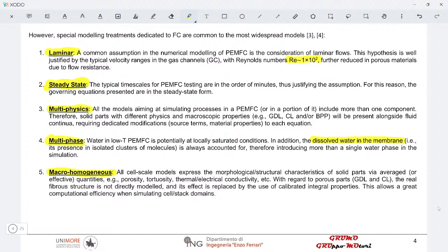And in those kinds of models, yes, if that is your focus, you have to replicate the exact structure of that material. In the type of models that we are considering here, we can't do this. The computational load will be just excessive, and what we can live with happily are just statistical, averaged properties of our porous material.